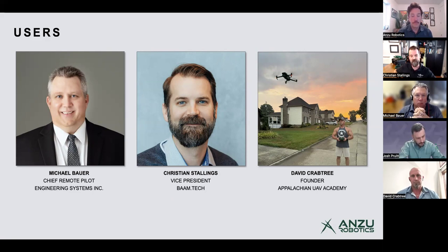Some of the other functionality that we wanted to test are important. Of course, RTK is great, but sometimes you need to post-process, which is common in mapping, post-process kinematic or PPK processing. Anyone that's done this with DJI products is familiar with some of the files it creates, the observation files, the navigation files. All of those files that you're used to were there. We were able to use a software that we sell called RedCatch to do our PPK processing. And again, everything processed as normal.